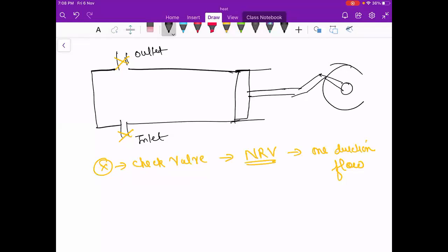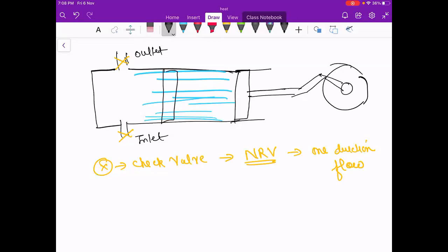So what will happen here basically, once the piston moves, it will travel a certain amount of distance. Suppose here it is filled with liquid. Then the next position of the piston will be like this. So it will give a pressure, but when it goes up, the piston will move back. If you see the water flow rate versus time, it will come like this, because this is the time during which you are getting the flow rate. But when the piston goes back, there will be no flow rate outside, so that is why it will come like this.